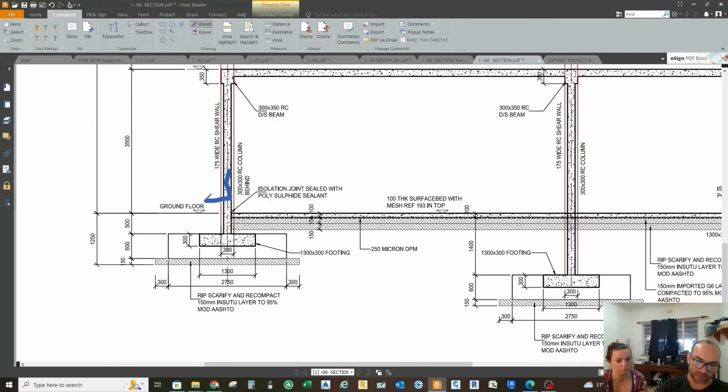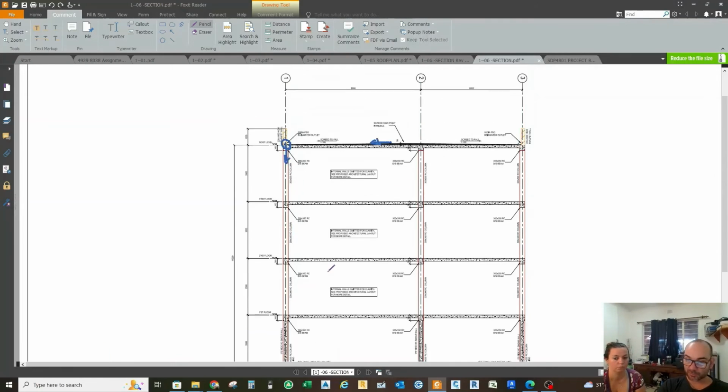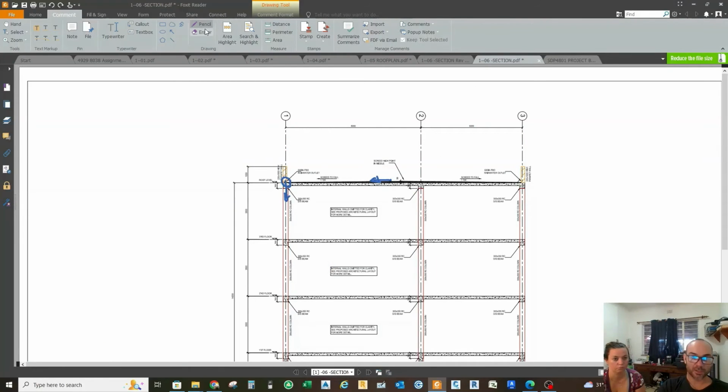The architect will provide guidance as to how the outlet detail should look, but very basically, there will be a pipe coming through the column, making its way onto the external stormwater system, from where the stormwater will flow into the larger municipal system or flow by means of sheet flow onto the external road system. This concludes the presentation.